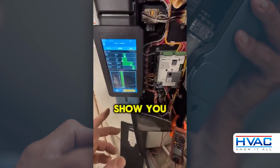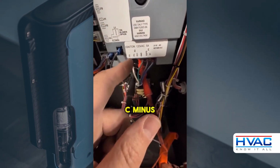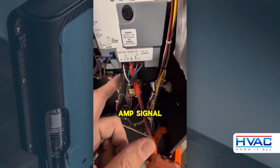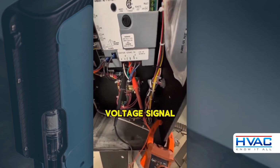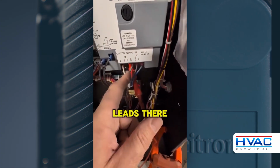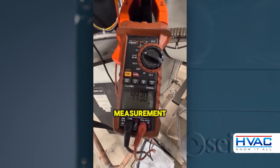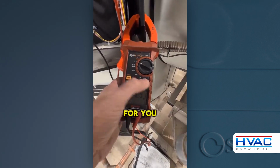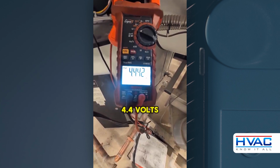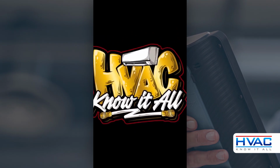So something else I'm gonna show you here, we can check our flame signal at FC minus and FC plus. Basically what happens here is that microamp signal will change to a voltage signal. It's referenced in the manual that it will do that, so we can put our meter leads there, set our meter to volts, and go into the DC voltage measurement, and we can see, let me turn the light on for you. So with the light on, we can see that we're reading 4.4 volts DC, but that is correlated from 4.4 microamps.